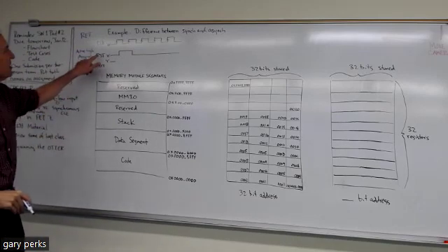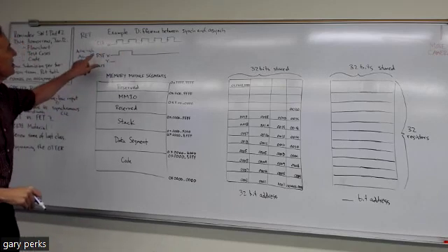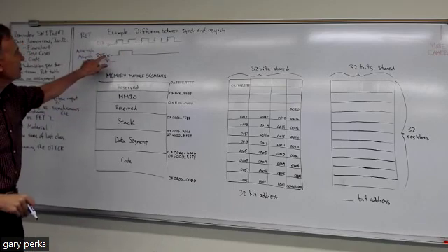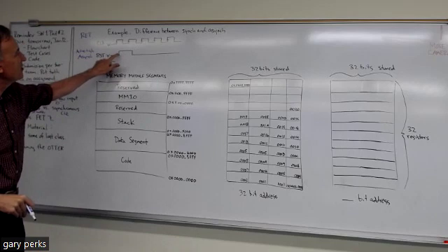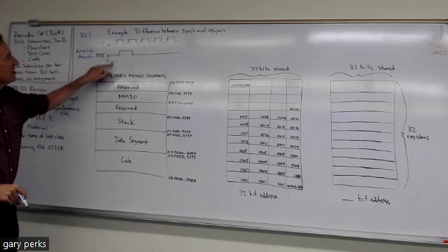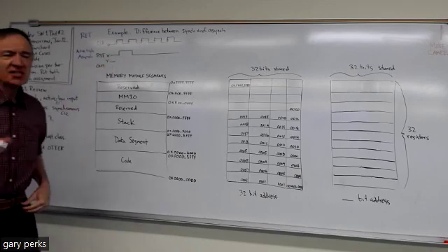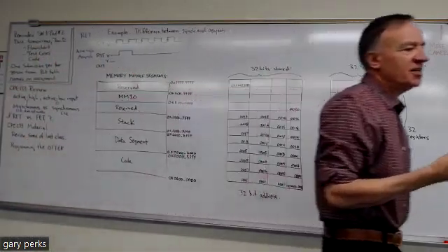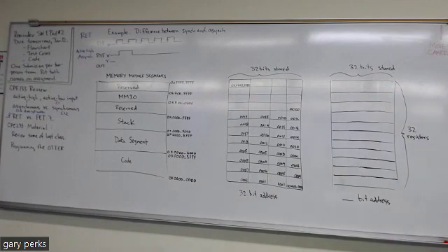So you can see here, here's our clock, like we said. Here's our reset, it starts at 0, and you see right at this time here is when it transitions 0 to 1. And here's our output, which is initially a 1. Also, you may recall from 133 that what we mean by reset is that when that input is active, the output's going to go to 0, right?